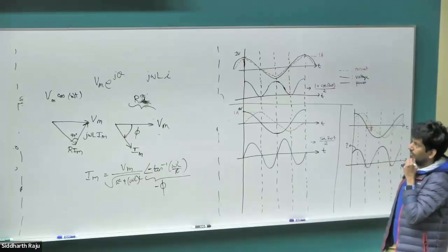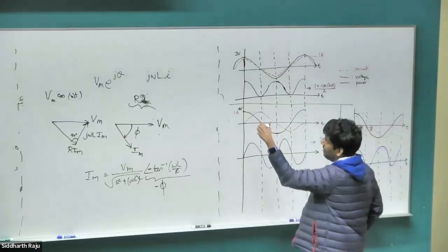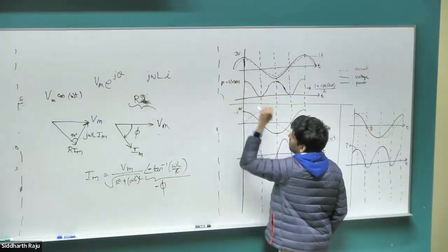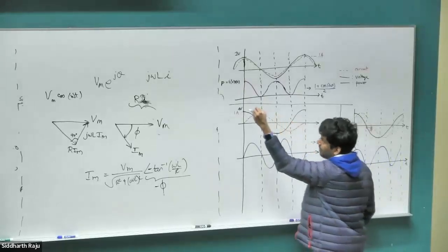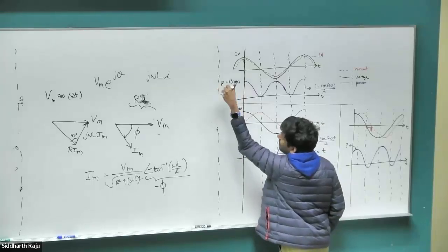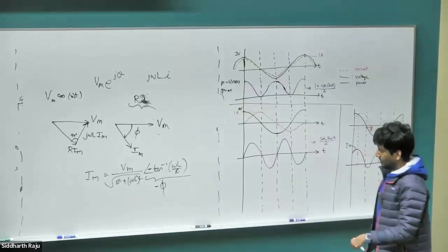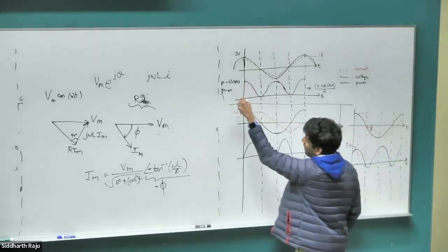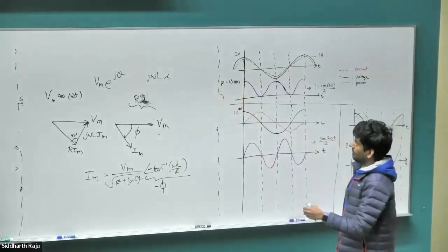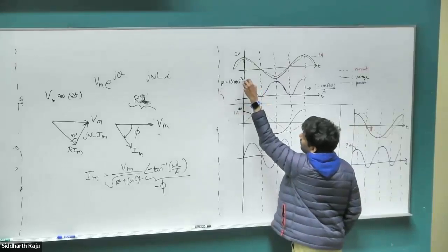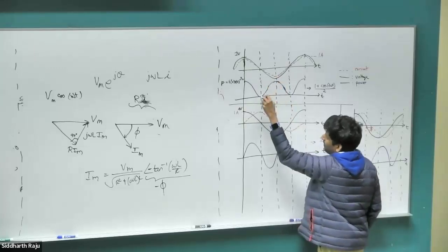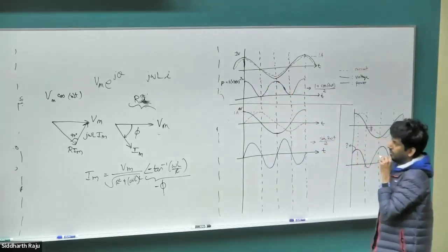Right? So if you look at the power, we have a definition already. We have a derivation already. That power at any given instant of time is I of t times V of t. That's something we derived from our mechanical system, where we had mass times the velocity. From that derivation, we figured out how to get the power in terms of the electrical circuit as I times the voltage. So once we have that, we can plot at every single instant of time what the power is going to be. Here it's going to be 1 watt, 1 times 1. And when both the current and the voltage go to 0, power goes to 0. When they both go negative, the negative product is again positive, and you end up with this diagram.